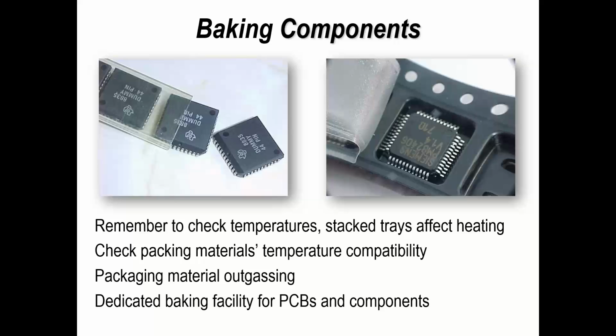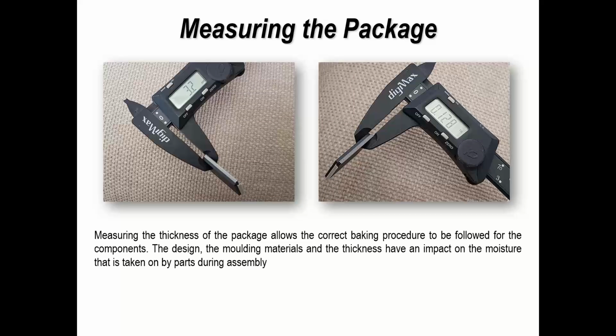Okay, so I mentioned components. You've got to think about compatibility. As I said, most of the packaging will not stand up to the baking temperature. If you find they will, then that's fine, but it's something you need to verify. Don't just do it, you need to verify it.